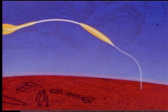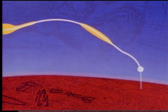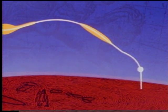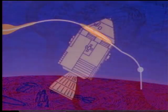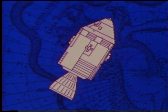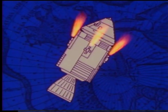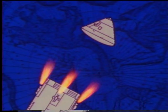The Apollo entry phase will terminate at about 23,500 feet altitude. At this altitude, the drogue chutes will come out, and the spacecraft descends to splashdown by parachute. Reviewing now, we see that before entering the atmosphere, the service module containing all but the entry oxygen and power supplies will be jettisoned, and the command module positioned in its trim alignment.